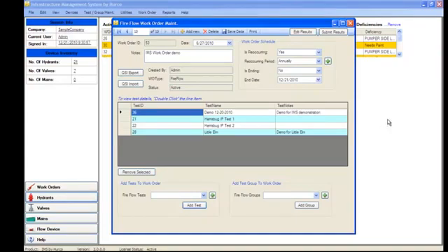Now, back to the work order. Once you've gone out and done your fire flow test and recorded your data either using the Hurco FireFlow Pro system or manually writing it on your report form for that particular fire hydrant, you need to bring that data back to the office. Now, if you're using the Hurco FireFlow Pro system, that system automatically syncs with the IMS software. The data will be transferred automatically, and the results of that test will be included in IMS software.